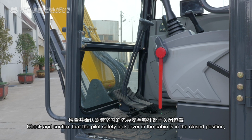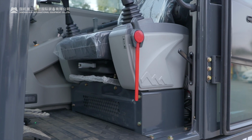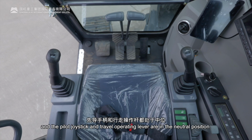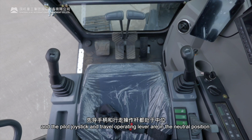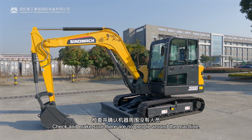Check and confirm that the pilot safety lock lever in the cabin is in the closed position, and the pilot joystick and travel operating lever are in the neutral position. Check and make sure there are no people around the machine.